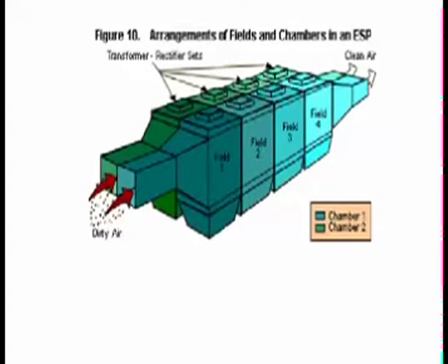Because the gas quantity may be very large, you don't want one large unit, rather you divide it. The idea of dividing into a parallel process will always have higher efficiency. If something goes wrong in one stream, and things can go wrong, you continue to operate the other. So generally you will see the ducts from the same generator divide into 2 streams, absolutely identical, and 2 ducts come out and connect to a large chimney. That is how your ESP looks like.